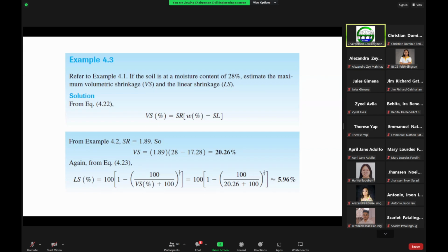In that 20-meter depth, we need to know if the soils have the properties of a liquefiable soil material, so we do an initial screening. For example, in the one I attended earlier, the liquefiable depth that we identified is about 18-meter depth.